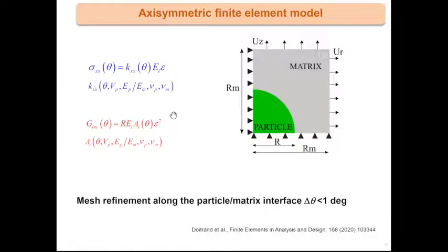Here we introduce a factor which is a kind of stress concentration factor, which depends on the angle and on the geometry. And here we introduce a normalized incremental energy release rate, which also depends on the angle and on the geometry. These factors are evaluated with the help of finite element calculations.